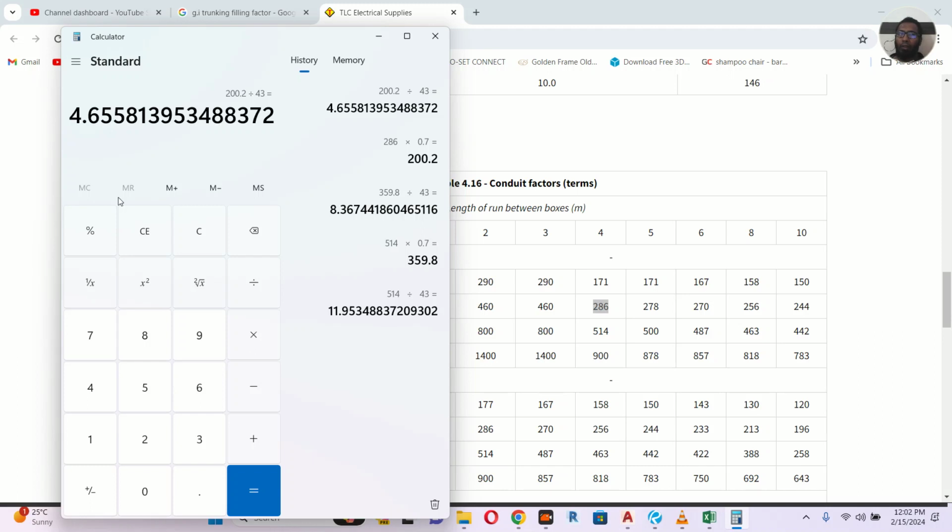If you want to take 6 wires, you have to go with the 25. This 20 mm we mostly use for lights. It can go for 5, and the spare will be reduced. If you have 3 circuits, 3 phase, 1 neutral, meaning 4 wires, and 1 earth makes 5. So it's almost 4.6, so maximum 3 switches. So 3 phases can come.